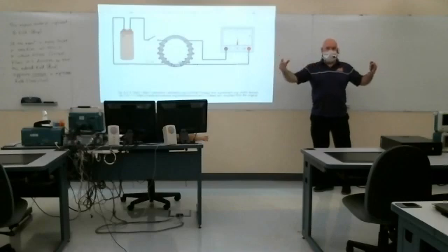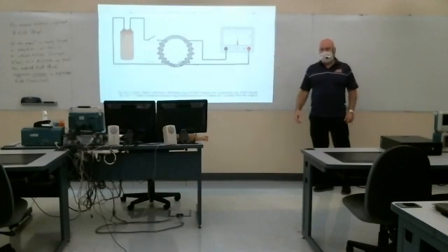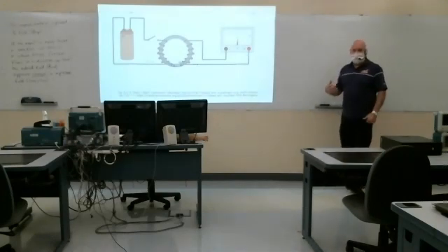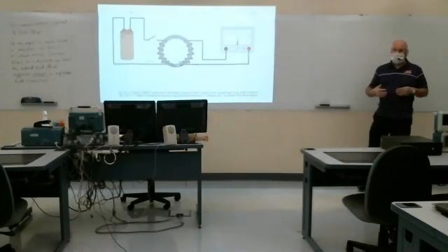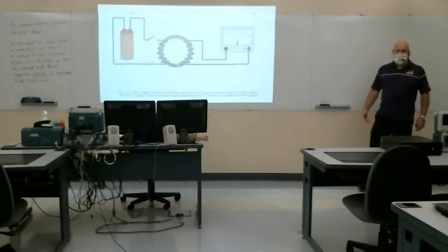You get power loss in the conductor, it's a function of the amount of current, and that's wasted power. That's just lost as heat in your transmission lines. So for power transmission, we want to transmit it at really large voltages, hundreds of thousands of volts. Now, that would be very dangerous to have that voltage coming into the house.